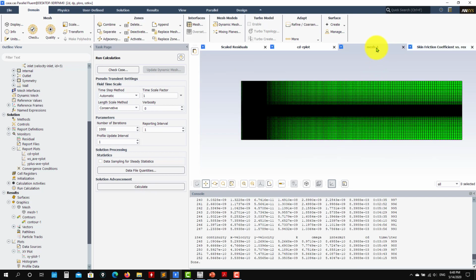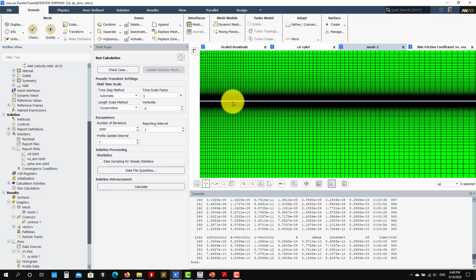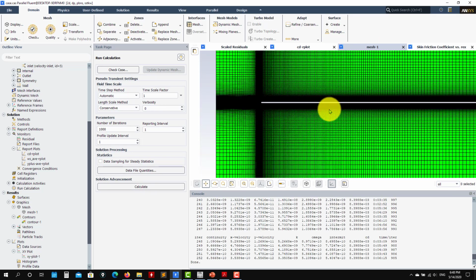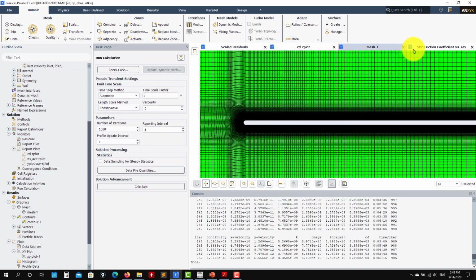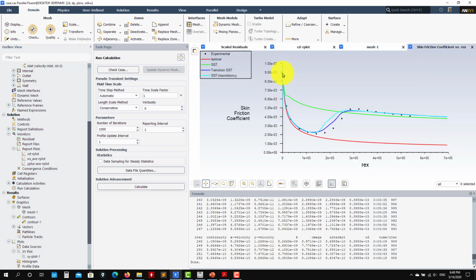Just to frame the problem a little bit, we have the classical flat plate. See that we have this flat plate, the flow incoming, and then there is some region where the flow is still laminar, and then you have the onset of turbulence, which you see here in the experimental results. In one simulation using laminar or DNS, you have the fit towards the laminar solution.